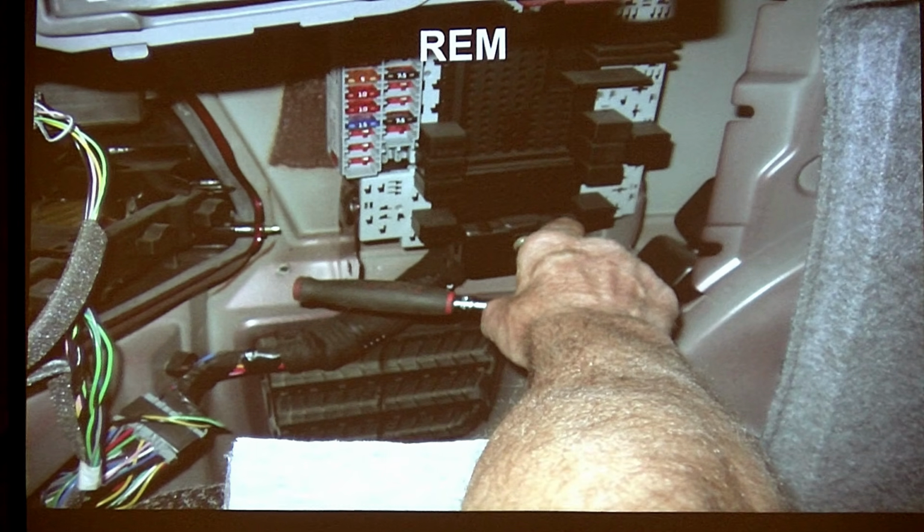I've got two wires that come out. I tee into both the wires. I dial 120 ohms, and now I've got enough for a termination resistor. I put it in. If I suspect I'm missing one, I put it in and see if I can fix it. Sometimes that doesn't work because they need to be on the ends. They're placed in a certain position for ringing.